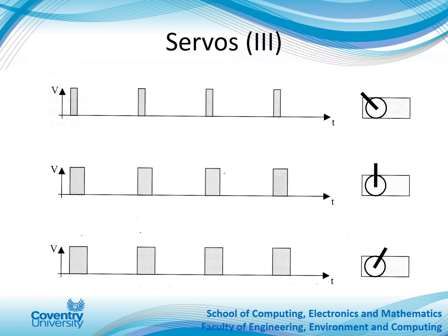Like stepper motors, which we'll cover in a second, servos are very simple and good for simple solutions in robotics. However, servos also have a drawback, same as stepper motors do, which is they don't provide any feedback to the outside. So when you're applying a certain pulse signal to a servo, you don't actually know whether it's reached its desired position or not, for example, if it's got a load that's too high, or if there's something in its way. So you need to come up with ways to compensate for that when you're designing your system.